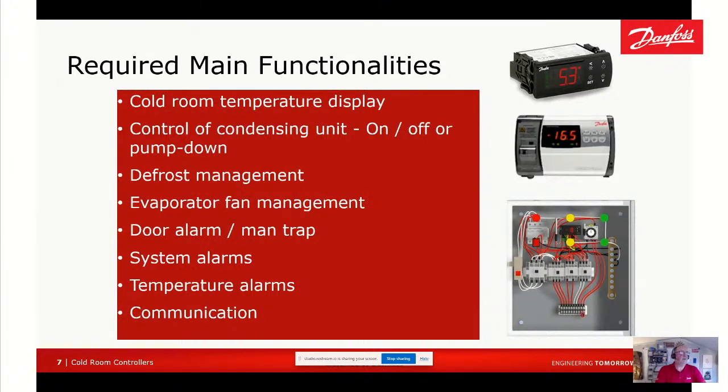So yeah, just thinking about the functionalities that we've got there regarding a cold room controller. I've put 3 pictures up on the side. We've got the typical Danfoss ERC little digital controller that looks after the evaporator. The second one down is the Danfoss AKRC cold room controller, like that one behind me, and on the bottom is a cold room control panel that you could get made up at a control shop, for example, or as I used to do when I was much younger.